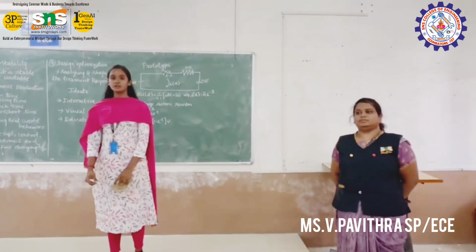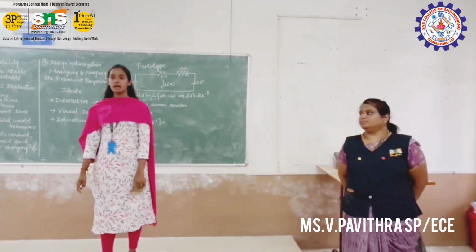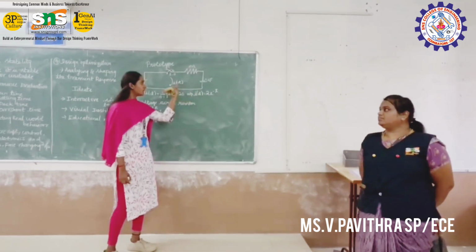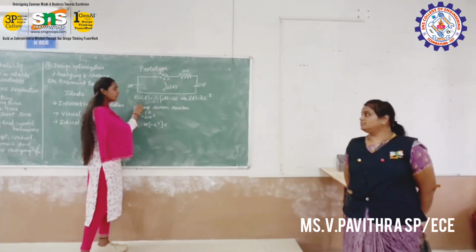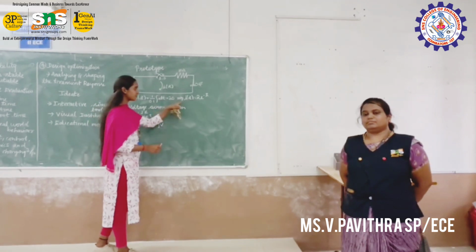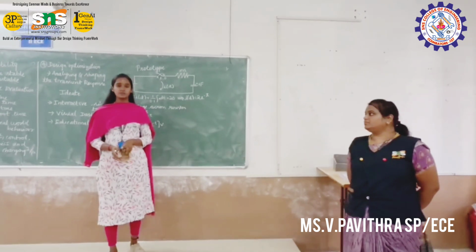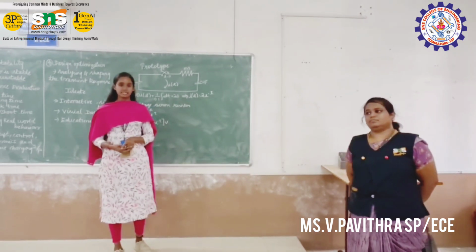Hello everyone. Today I am going to explain the prototype of the transient response of an RC circuit in DC. From this given circuit we can see that this is an RC circuit because a resistor and capacitor are given. So this is the transient response of an RC in DC circuit. This is the main equation. By applying KVL we get this equation. After applying the Laplace transform we get i(t) equal to e to the power minus t. The Laplace transform is nothing but this: the given circuit is in the time domain, and we have to convert it into the frequency domain. That is known as the Laplace transform.